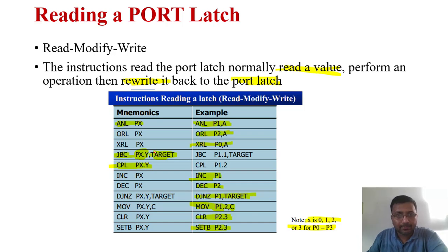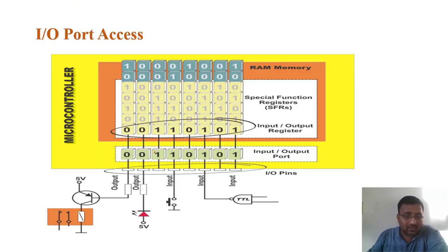Okay, all right, so this is IO pins controlling states. What is there inside the microcontroller? We have internal input output registers available that hold the data. Then we have special function registers, which are updated with this particular internal register. And there is a port register available, so with this port register the data will be transferred into the buffer first, and then that buffer will be loaded into the appropriate special function register. So we can attach any of the inputs and outputs, and we can configure separate bits accordingly.